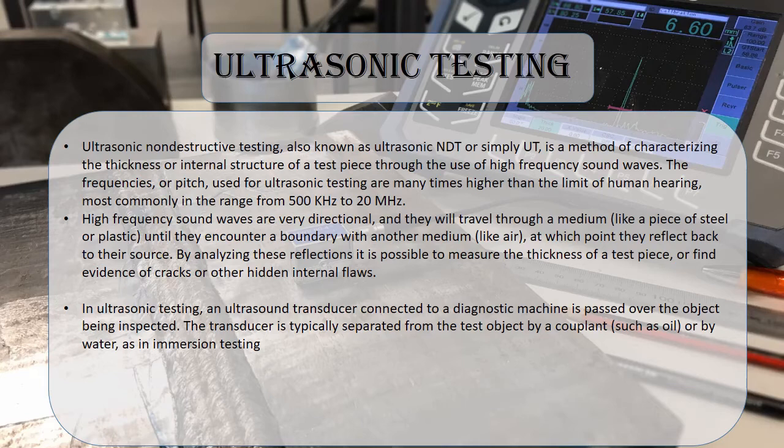In ultrasonic testing, an ultrasound transducer connected to a diagnostic machine is passed over the object being inspected. The transducer is typically separated from the test object by a couplant such as oil or by water, as in immersion testing.